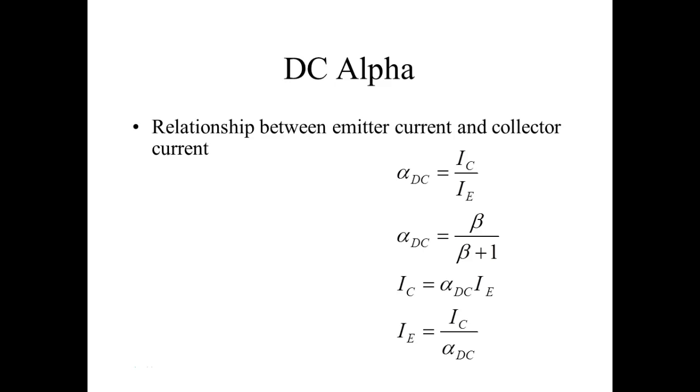But they don't give the alpha in the data sheet. And why? It's just like they don't give us IZ max in the data sheet. They give you the maximum wattage and the Zener voltage, and if you understand electronics, you know that I is equal to P over V, so we calculate the maximum current. Likewise, they don't give us the alpha because it's so easy to calculate.